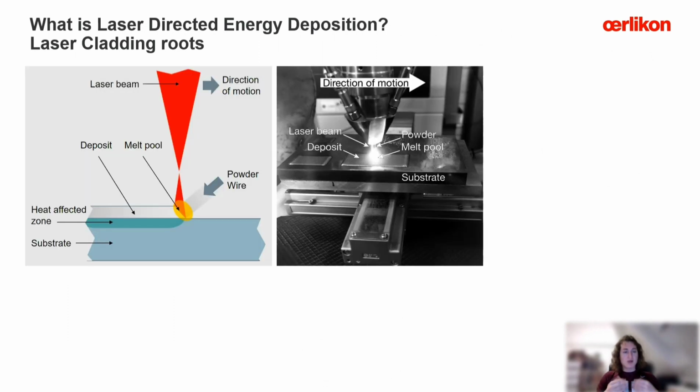Before we try to understand the technology, let's take a look at the roots together. And the roots of directed energy deposition are all in laser cladding. And as you know from my channel, I quite a lot explain what laser cladding is. Anyways, let's repeat and see that in laser-based directed energy deposition, we use laser as an energy source. And we focus this laser on the surface of our component or substrate or previous layer, and then start to add there a filler material.